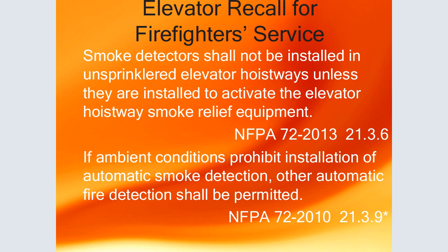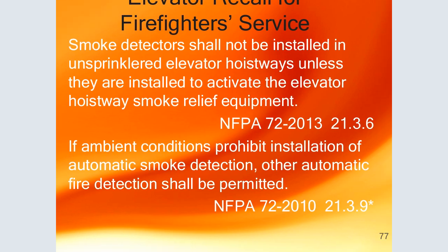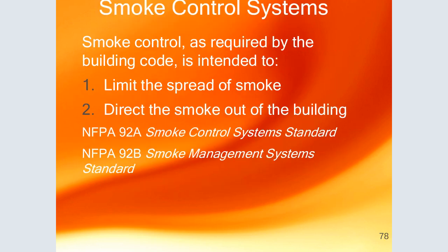Now, elevator recall for firefighters. A smoke detector shall not be installed in a single elevator hoistway unless it is installed to activate the elevator hoistway smoke relief equipment. Where ambient conditions prohibit installation of automatic smoke detection, other automatic fire detection shall be permitted.